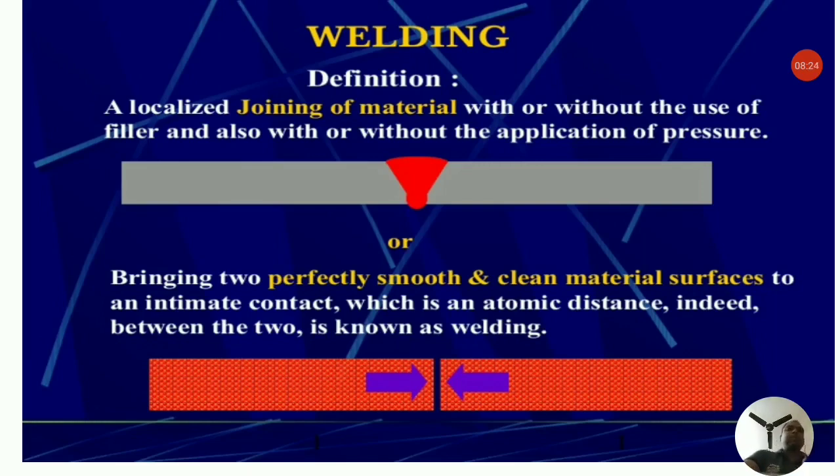Now the joint for adhesive application should be properly chosen to provide the necessary cleanliness and the required surface roughness. The type of adhesive chosen should take into account the geometry of the joint, the type of load application, working conditions such as temperature, as I earlier told you, and also the humidity. Now the adhesives are normally applied by either brushing or spraying. The adhesive joint should be cured after assembly by simple air drying or more commonly using a baking process. The temperature and time control during the curing process is vital for the development of proper strength as well.